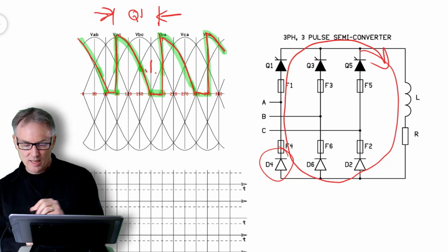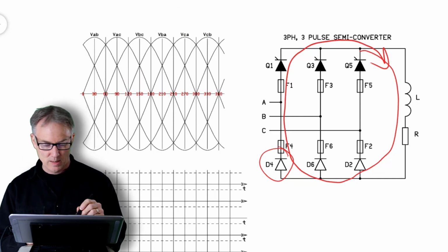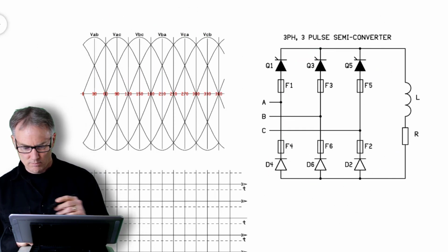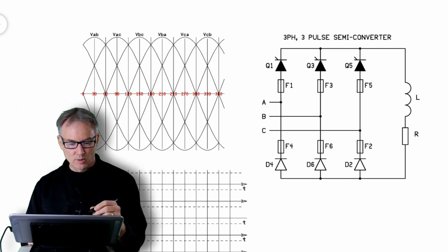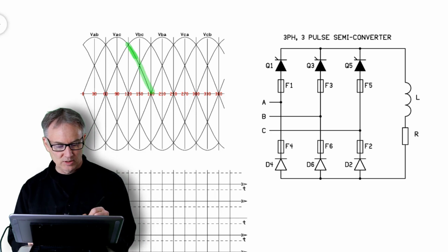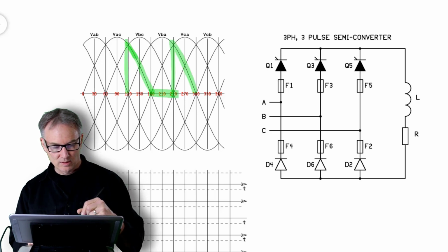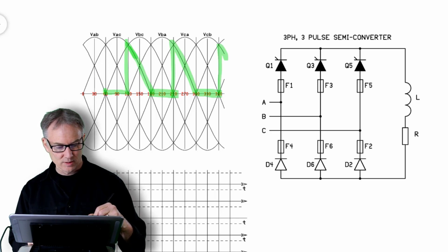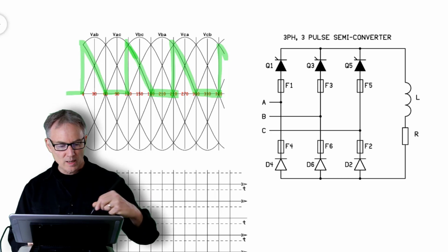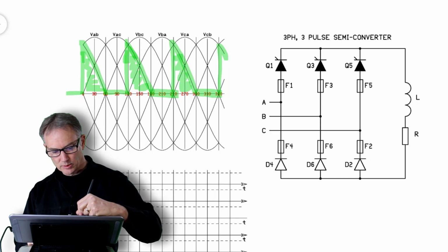Okay, so now let's look at going back further. Let's phase back to 120 and see what that comes off looking like. So 120 degrees means I'm first turning on Q1 here. And now I've only gone 60 degrees. I still have to go another 120. So you'll notice that the waveform is really starting to come down faster here. Okay? So this is basically what your output voltage is going to look like. It's going to be a bunch of little spikes.